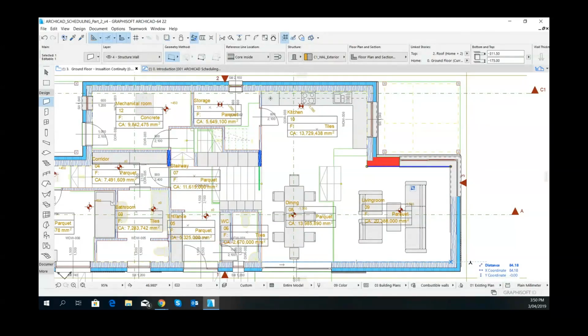So if you set up a wall correctly to start, next time you place a wall, it should just inherit those parameters, and you only have to change the ones that need to change, and then you carry on, rather than avoiding them altogether and then coming back later on and trying to fix it. But that said, they are reasonably easy to fix up with things like schedules as well. So like all this data, you can pull up a schedule and it'll show you all the things that you want to see, which you can then go through and change in the schedule as well. So again, that's sort of double work. So try and get it right.